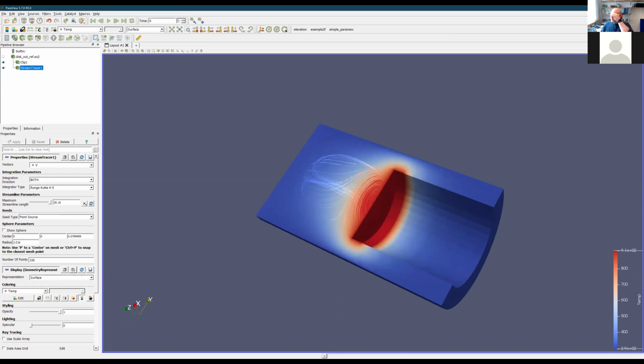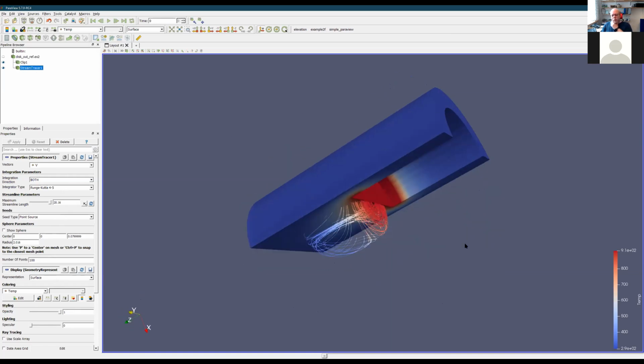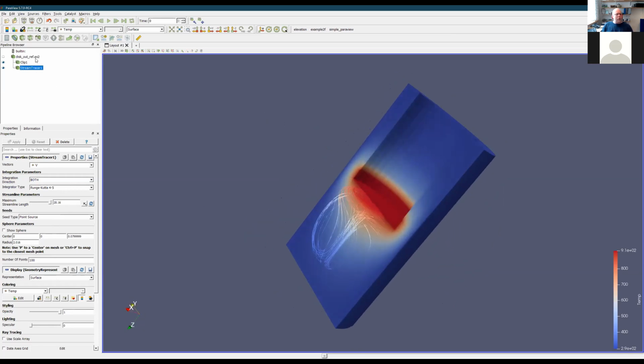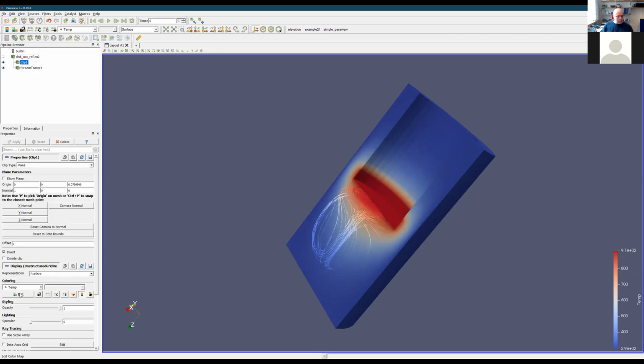So what we also can do is change, for example, the stream tracer to use lines instead. Okay, so now we have this. Perhaps we don't like the color scales here. We can edit that as well. So we go back here to our clip plane. And then we edit the coloring. It says now it colors from the temperature. So we can edit here.